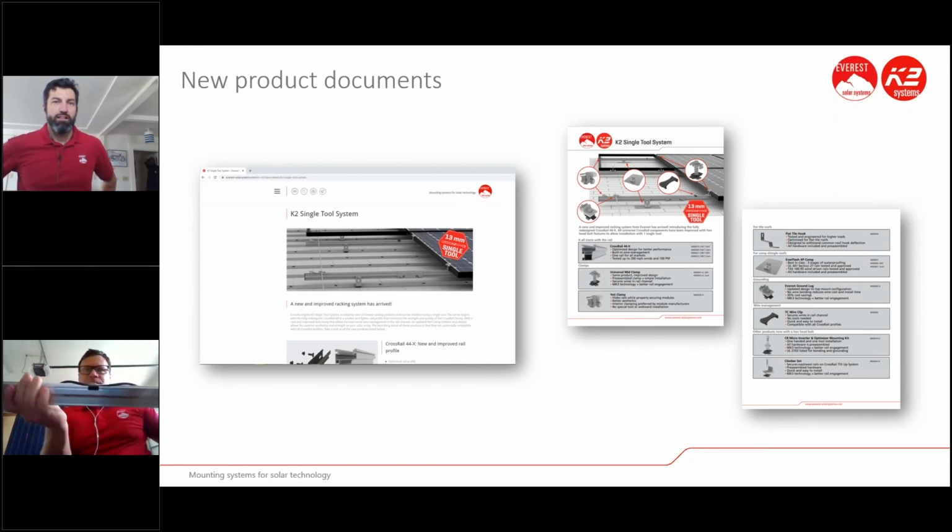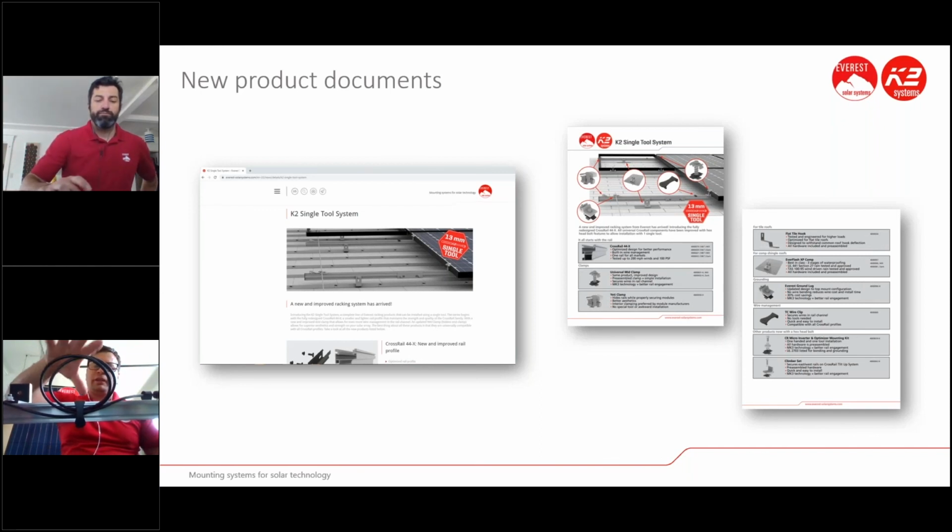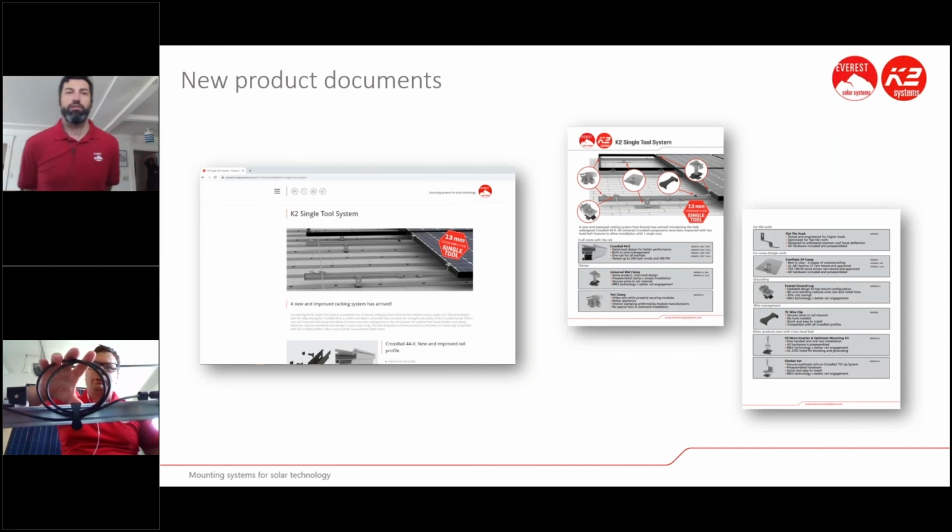The TC clip clamps to the top. So you have the option of putting wires on the side channel into the top channel, and then putting your MC4 connector in there as well. At the TC clip, you can also do these nice looms right here. This is very supportive for making sure that your leads aren't drooping down on the roof.